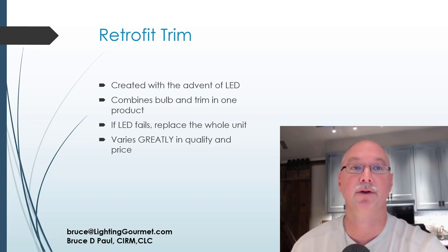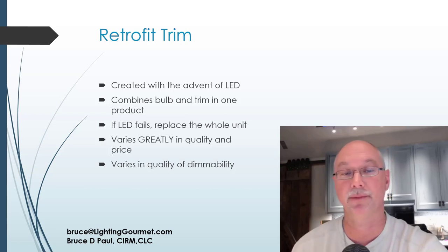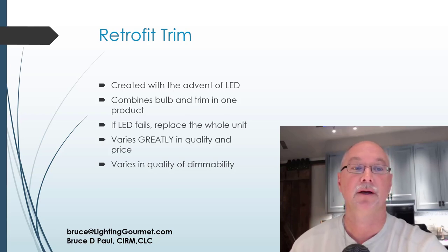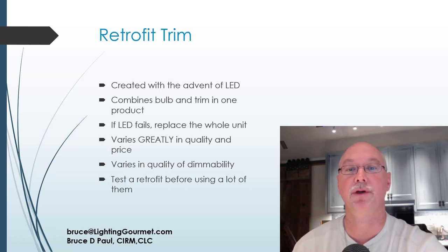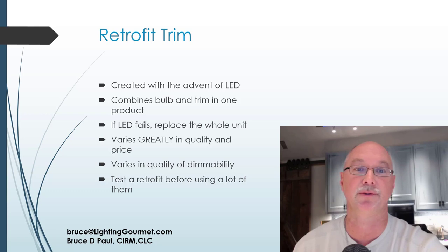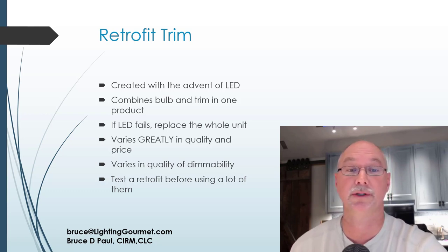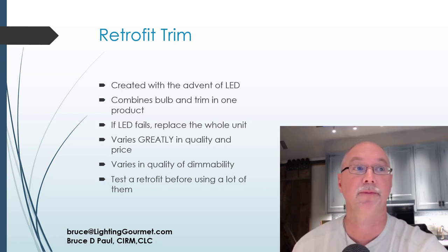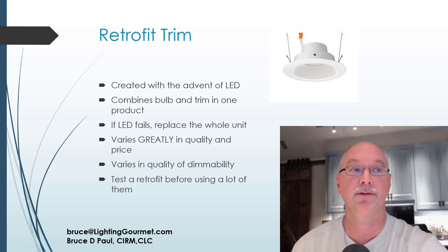Dimmability, color, etc. If you're going to use retrofits, look at my retrofit video. It'll help you on that. And dimmability is really important. It might say dimmable, but if it didn't cost $10, it probably does not dim very well. I like to just tell people, test it before you use a lot of them. No reason to install 40, 50, 100, and then find out that it really doesn't meet your needs, or it doesn't work well with your existing dimming system. And here's a picture of my favorite current retrofit. It's made by Juno, which is owned by Lithonia. And again, if you watch the retrofit video series, you'll learn a little bit more about that.